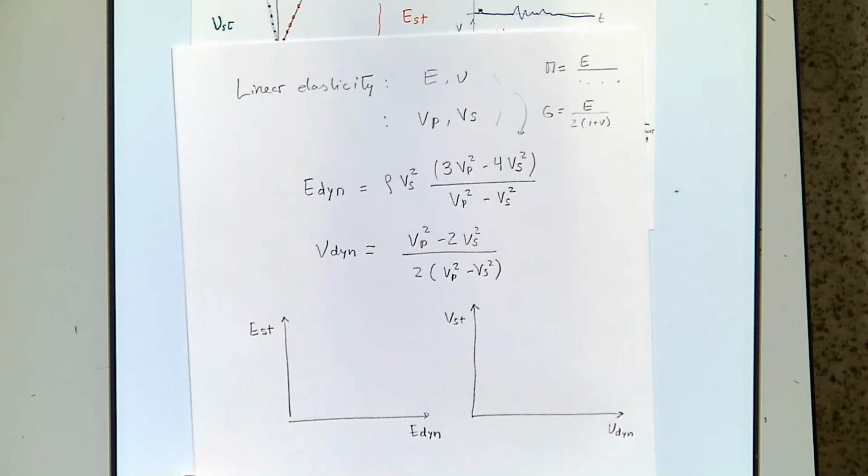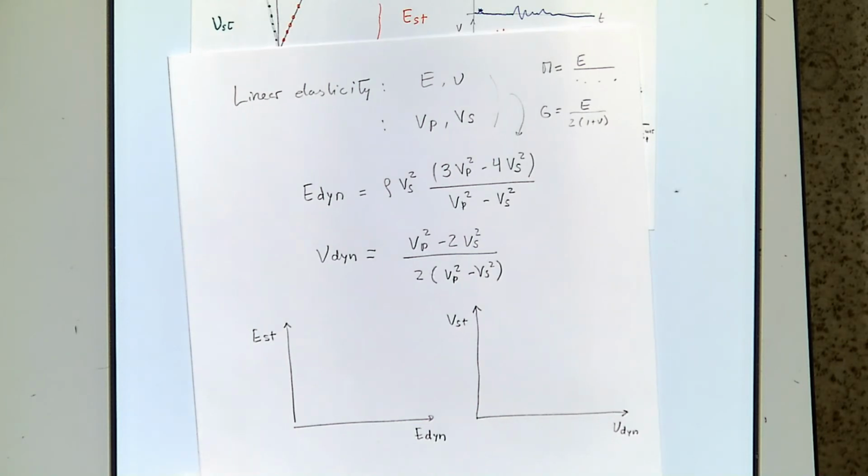Actually, Poisson ratio measurements in triaxial tests are kind of sketchy, iffy. I don't know how you may call it. With waves, it's fantastic, okay? But for larger strains, it's very complicated, okay?